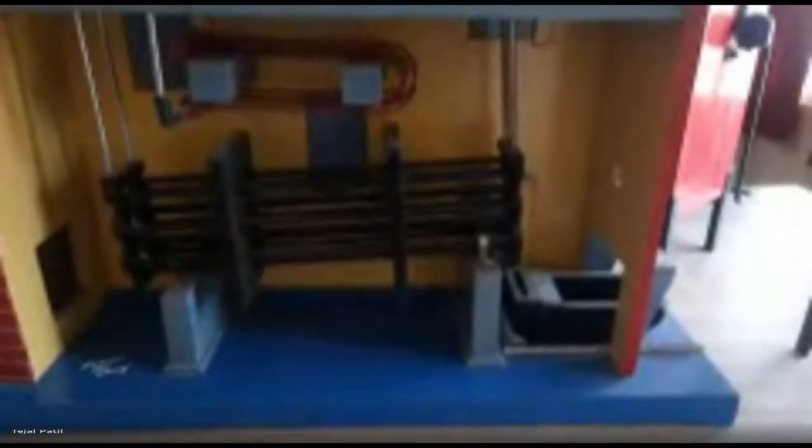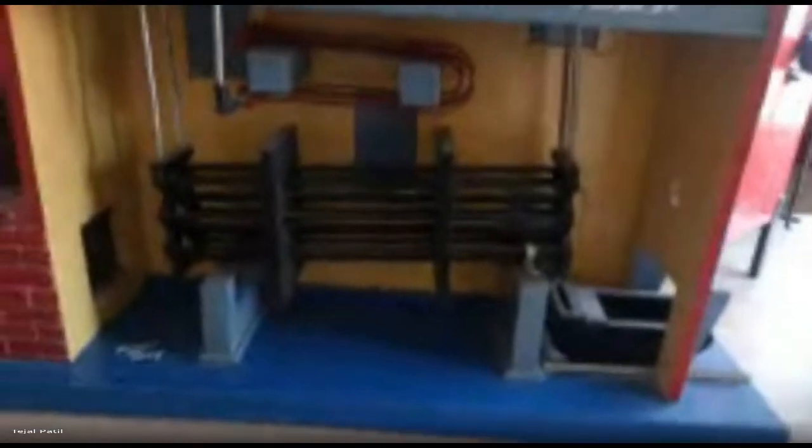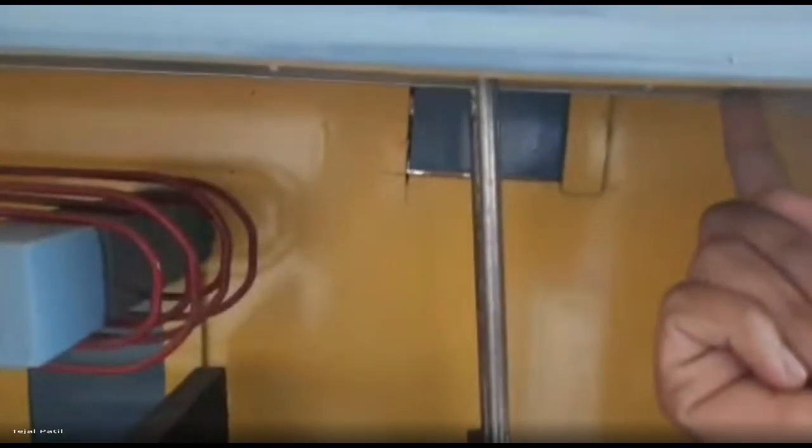So the fusible plug is made of a metal which will melt as soon as the temperature of the boiler reaches the highest limit. That fusible plug, which is located exactly at this location above the grate, will melt. And what will happen when it melts? As the fusible plug is there inside this boiler shell,